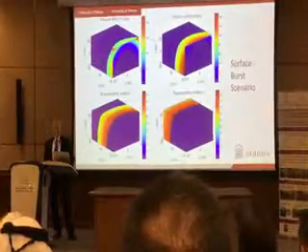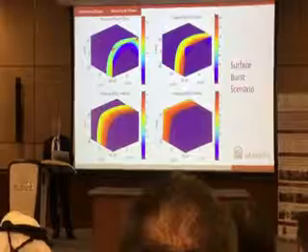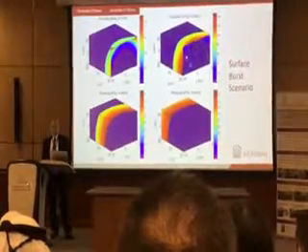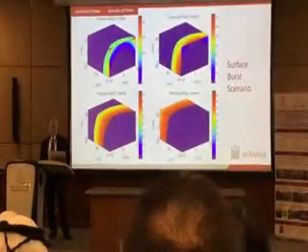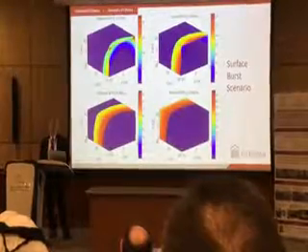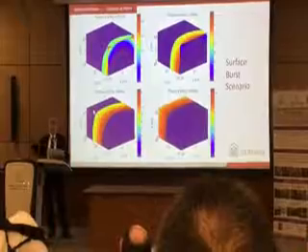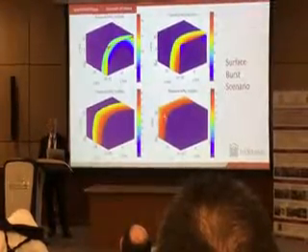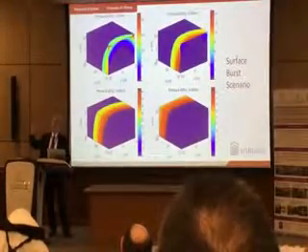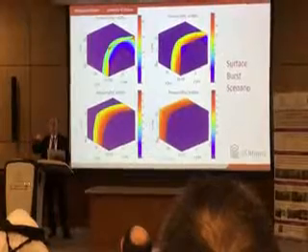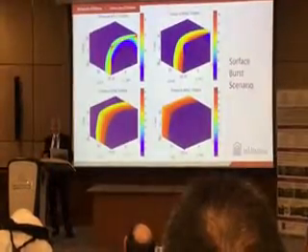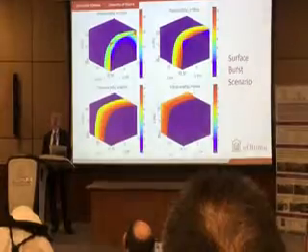And then it starts going towards the other side of the building, as you can see. Now there's no reflected pressure here, but there's incident pressure on the side walls and the roof, and it keeps sweeping the building depending on the shock wavelength. And then it may start affecting the rear wall, but with some time delay, and this is now 60 milliseconds after the explosion.